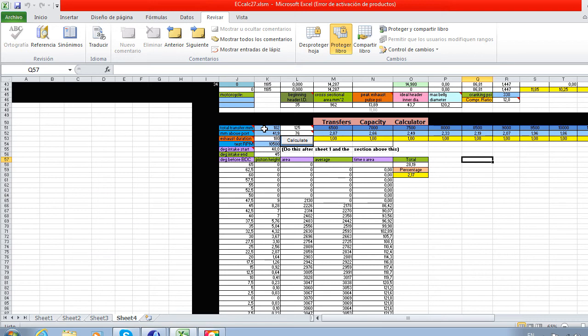If you don't know that, it's not critical. This right here is a typical value for when it's got really generous porting, like in a racing engine. And this is like for more old style engines that have one main transfer on each side of the cylinder and a boost port.